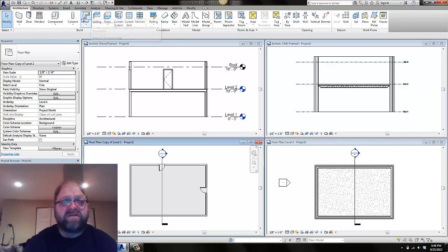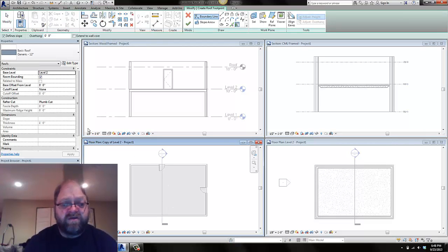Or likewise, if I put in a roof, and I connect it up to the roof level here, and I use the walls, and we'll define slope all the way around. That's fine. I'll give it an overhang, maybe of 1 foot. So again, I'm using some domain things. I'm inputting it by using pick walls, and I'm giving it something called an overhang, which only means something to somebody working in the building industry. Or I'm using this check mark, define slope, right?